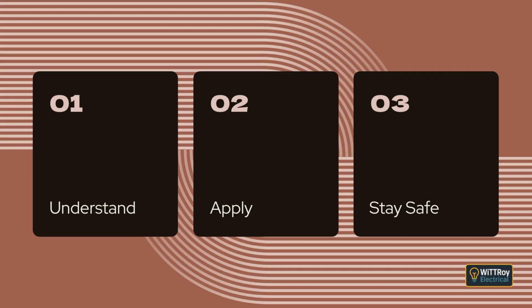Clause 3.7.2.1.1 Common Requirements. This clause reinforces that the above factors must be considered so the connection remains electrically sound and the insulation remains effective. Moisture control must also be considered to stop water entering the joint or moving along conduits or enclosures.